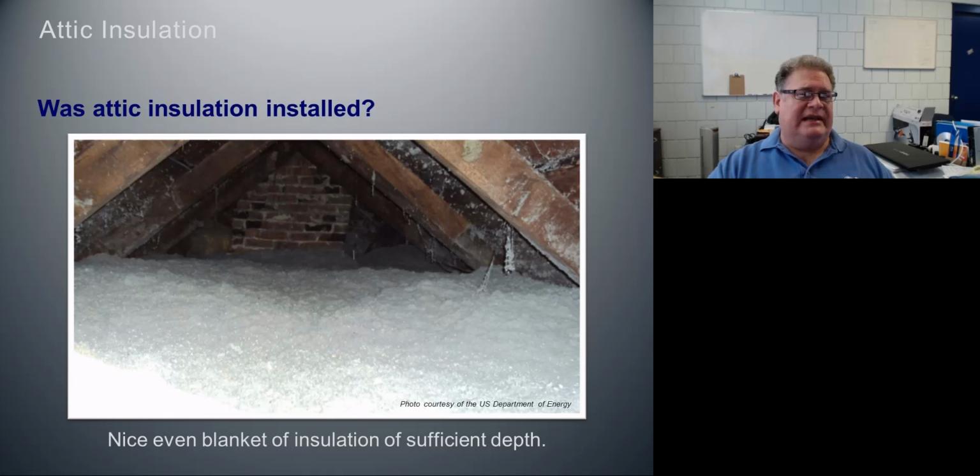We can look at the bag counts and determine whether or not we have the proper amount of insulation installed per the work order. Okay, so let's assume that 1 bag of cellulose will cover about 18.3 square feet of attic floor to get to R40. 1,000 square feet would need about 55 bags to get R40 throughout it. That's assuming there's no existing insulation in there. So that's one way that we can tell whether or not we've gotten to the R40 in that attic.